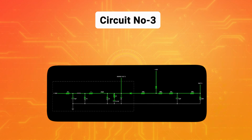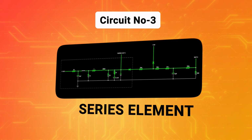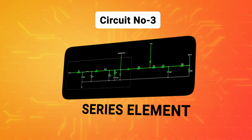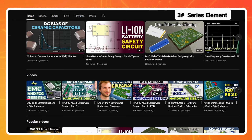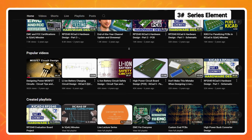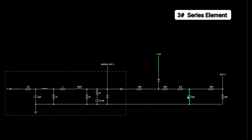The next element I'm going to show, similar to the electrolytic, is not really a protection circuit or a protection element, it's just a series resistor. And I have it labeled as a series element because this also could be an inductor. I've talked in a few of my other videos about how much I like using series resistors, both on input power supplies as well as signals going to a microcontroller or other parts. So I removed the electrolytic and it's just the 2 microfarad capacitance.